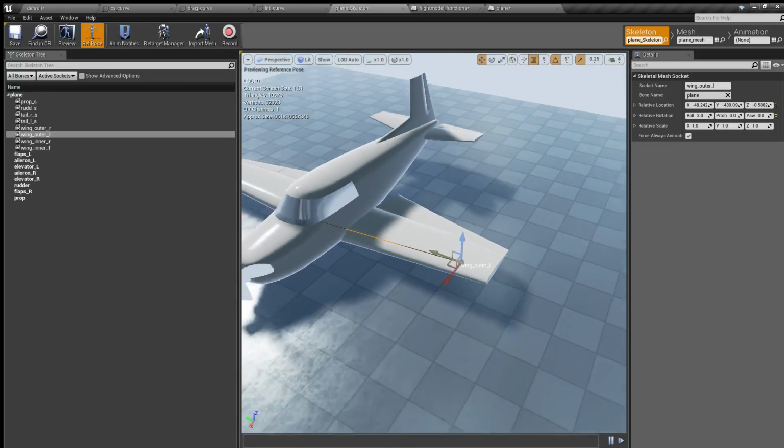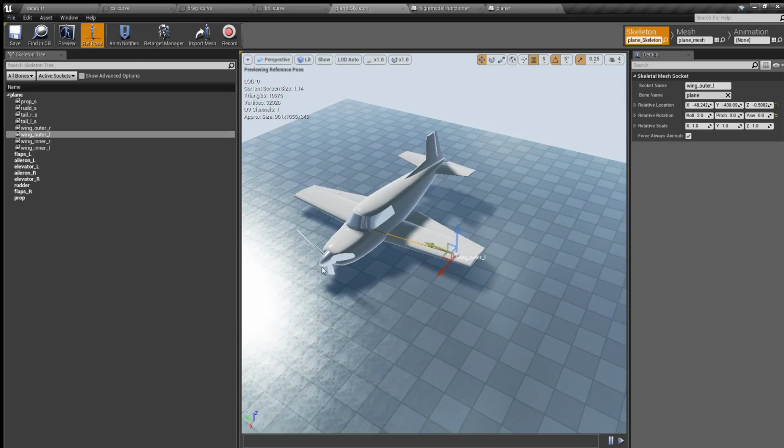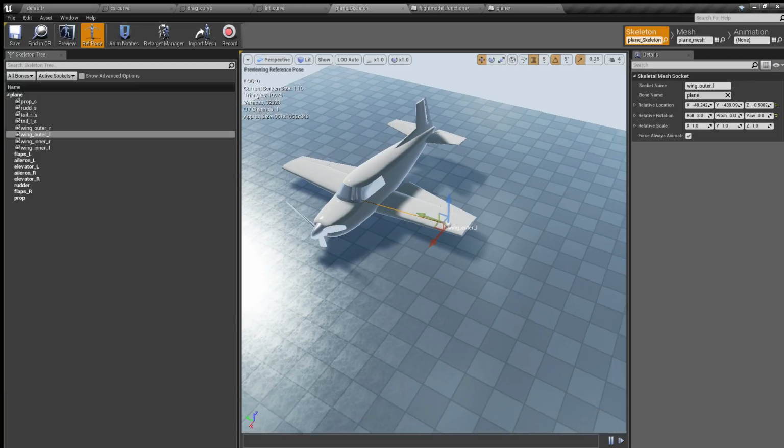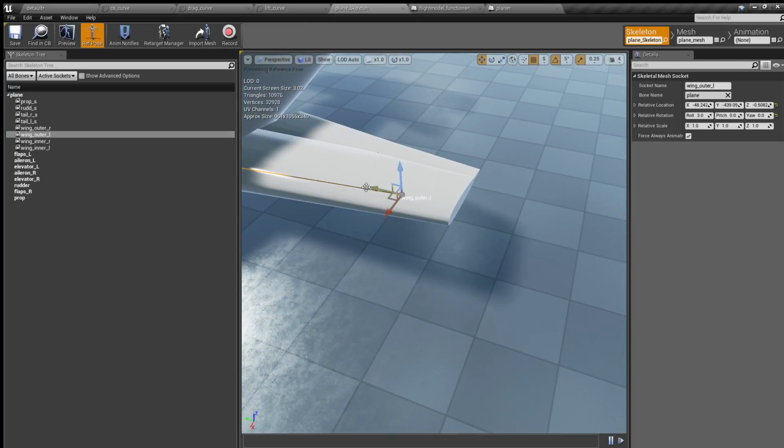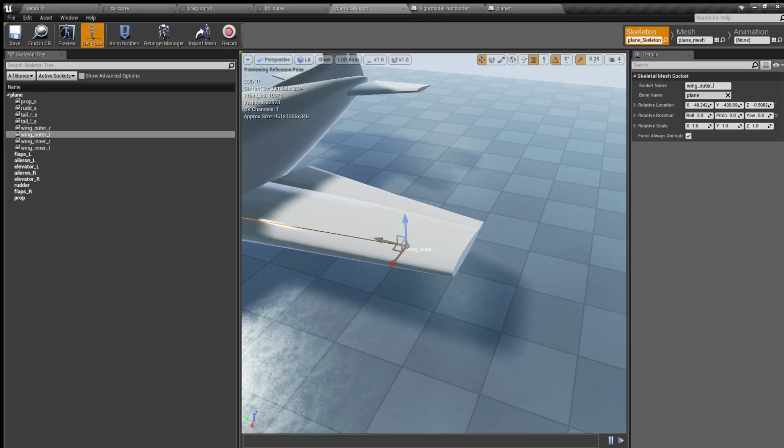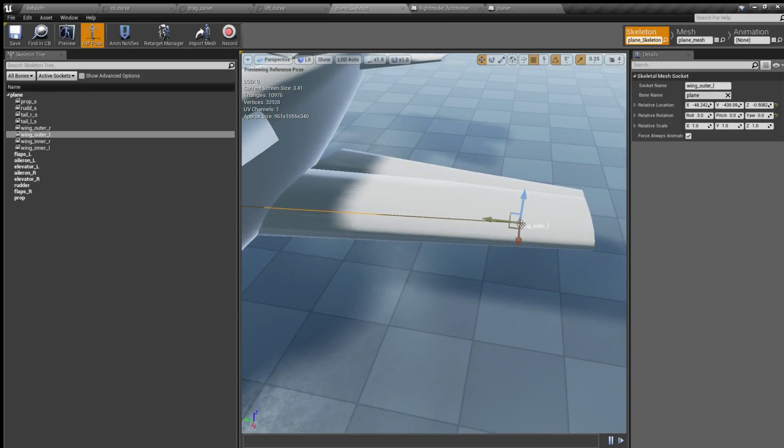So if you make an exact replica of the real aircraft, it will be slightly lazy in the roll axis compared to the real one. So as a compensation, you may want to move the socket of the part of the wing that contains aileron a bit more towards the end.